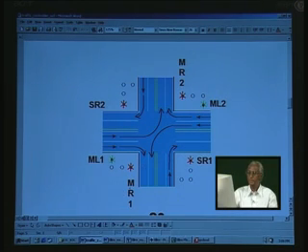Say, for instance, the main flow traffic has just commenced. If you look here, the 2-digit display will initially be set to 50 seconds, because we have 45 seconds plus 5 seconds transition, which goes straight here. After this the same counter will be reset to 25 and allow this traffic flow, and this is inclusive of 5 seconds once again for the yellow light, and having done that, the total is 75 seconds.